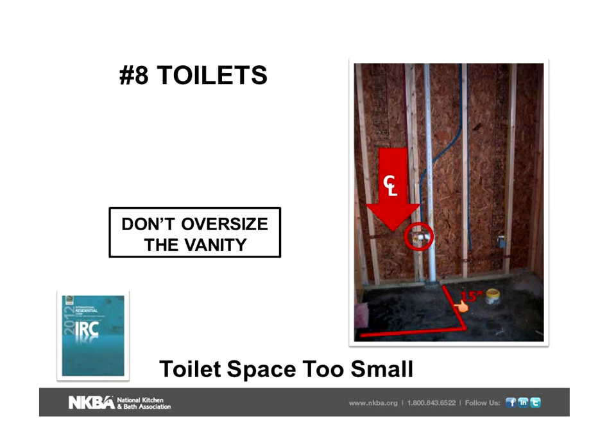Got a question? I'll pick that up in just a second. Looking right here once again, you measure this and you may say a 30-inch vanity works. So you order a 30-inch vanity. Unfortunately, it sticks out here another 3 inches, leaving 12 inches for the toilet, which is a violation of the code.